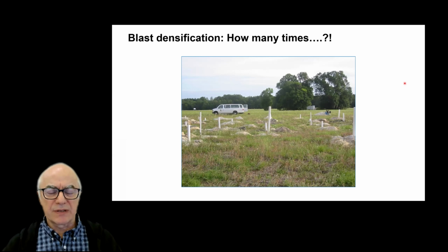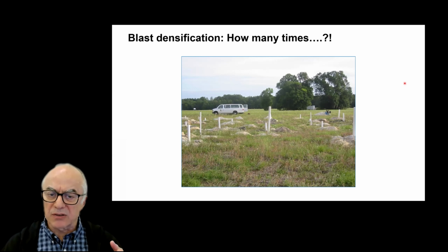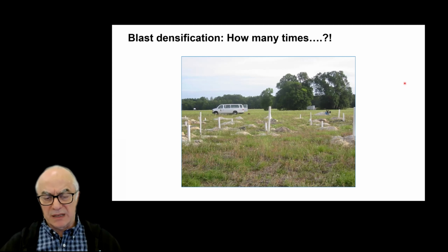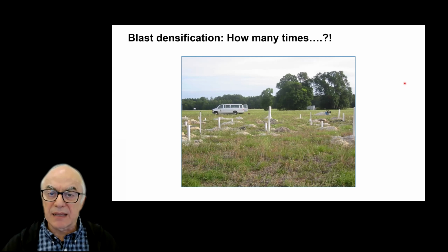Of course, liquefaction is a complex process, and in every cycle of liquefaction, all the upper layers resediment. So only the lower layers actually get denser, and the upper ones are, once again, resedimenting like a freshly deposited soil. But still the question remains, how many cycles do we need to do?